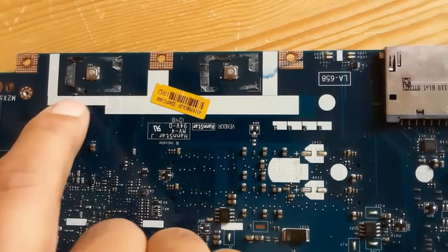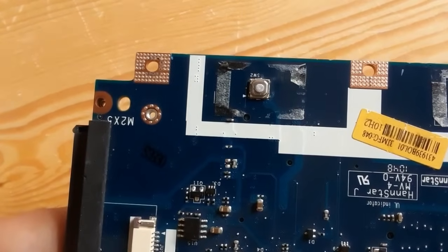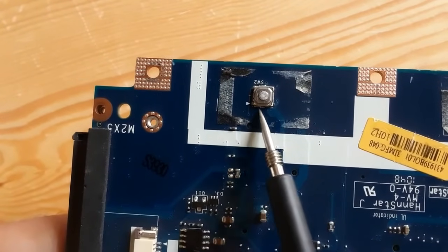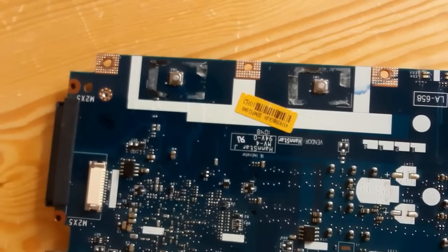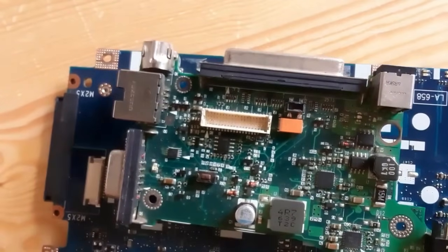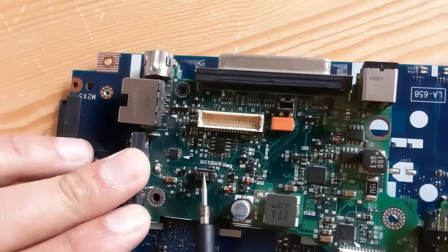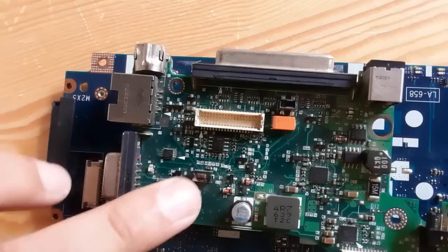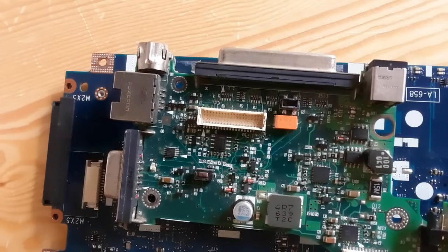The power switch, okay? When you troubleshoot your laptop, you should always check the power switch. Normally, the power switch contains 2 terminals: a negative terminal that is connected to the ground and a positive terminal that is connected to 3.3 volts. Because if the 3.3 volt does not exist at the terminal of the power button, you cannot switch on your computer even if you press the power button.